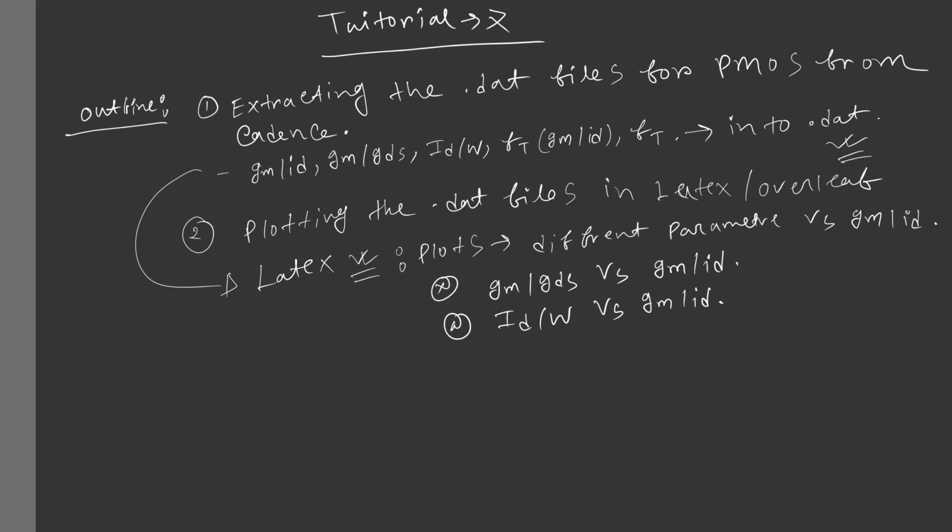Like that, every important parameter we will plot against GM over ID for PMOS. These plots are very important for the GM over ID based analog design methodology. So this is the outline of today's class.